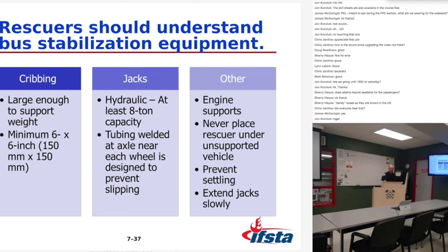Hydraulic jacks. There's a tube welded on the axle near each wheel designed to accept the shaft of a jack to prevent slipping. Engine supports can be jack points. And again, lift an inch, crib an inch.